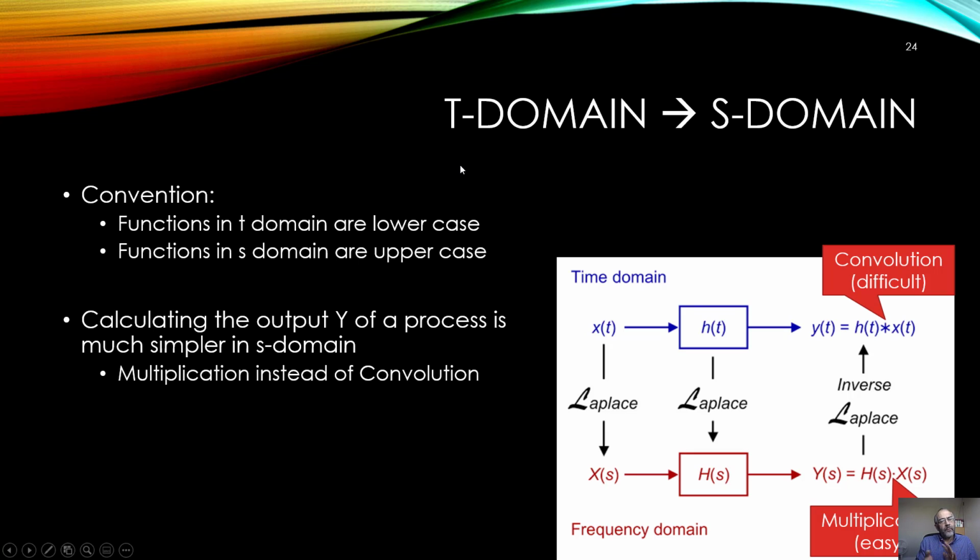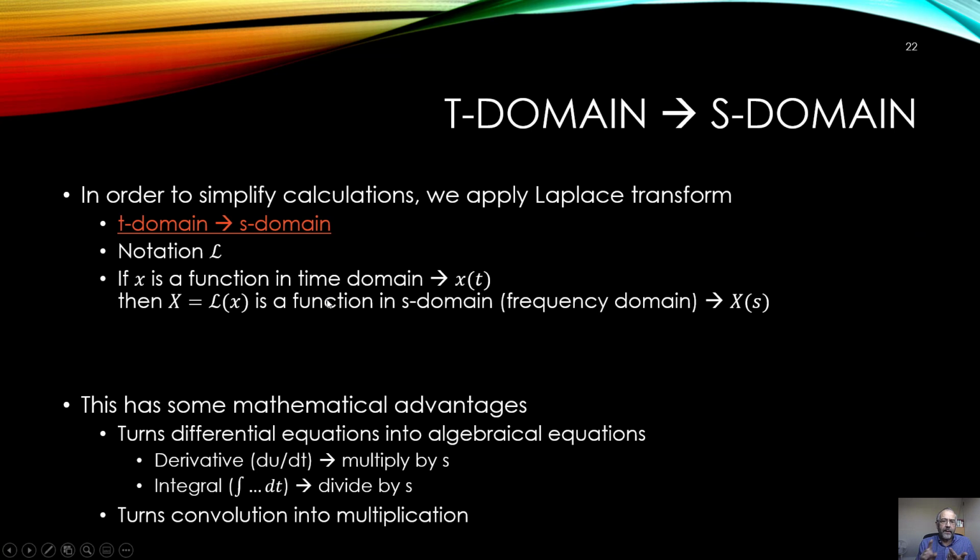Okay, then what is the advantage of going to the S domain? Again, a derivative becomes multiplying by s, an integral becomes dividing by s, and a convolution becomes a multiplication.